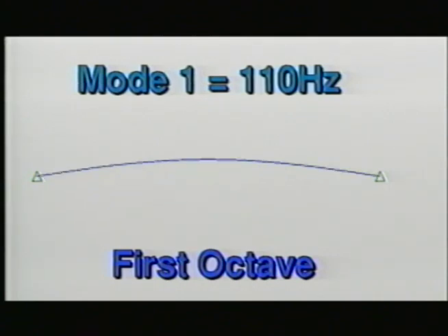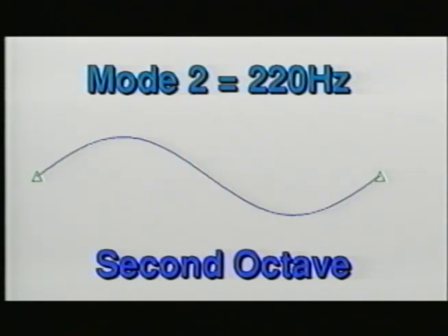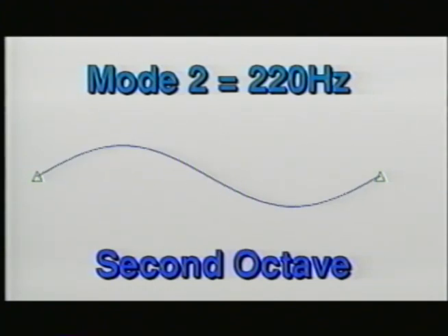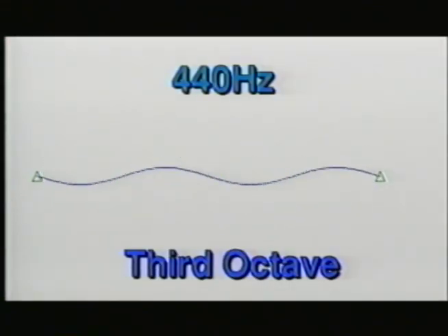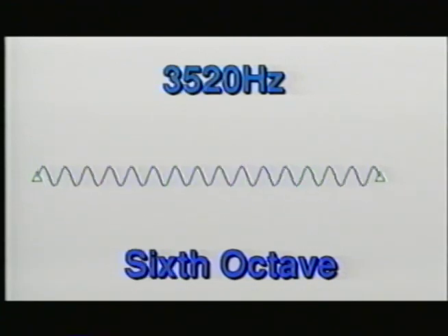Now we can plug the data we have gathered into the load stiffening module, which predicts the first vibration mode at 110 hertz. The correct result. Note that the second mode is one musical octave higher at 220 hertz, and so on up the musical scale.